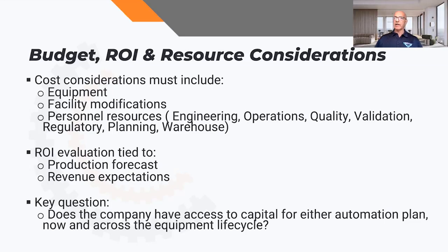GAMP is good automated manufacturing practices. GMP is good manufacturing practices, which tells the company how to document the production of the part. Good automated manufacturing practices is really the process of documenting, and it's a fantastic question, by the way, to document the complete process, going from your requirement stage, writing the user requirement documents, to get the quotes, to go through the functional requirement documents and then functional design documents, moving all the way into FAT, SAT, and then the validation activities.